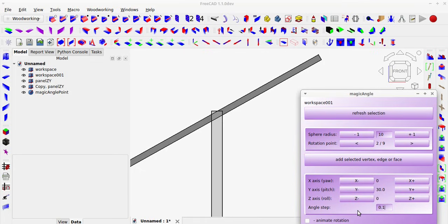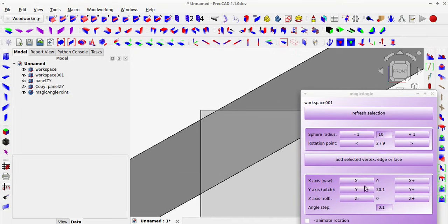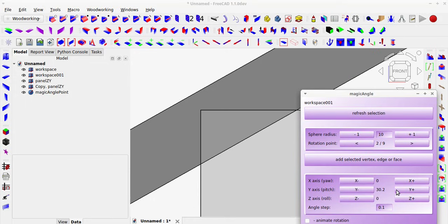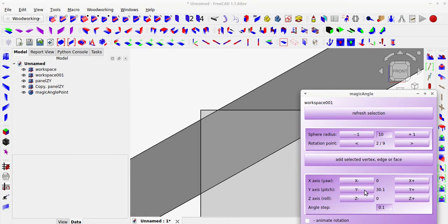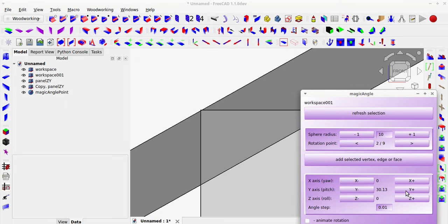If you're creating walls under a sloped ceiling over a long distance, it's probably best to avoid measuring the angle of the top surface. Angular measurements are imprecise, and at large distances it's unlikely you'll actually be able to achieve the precision necessary to perfectly align the other side.